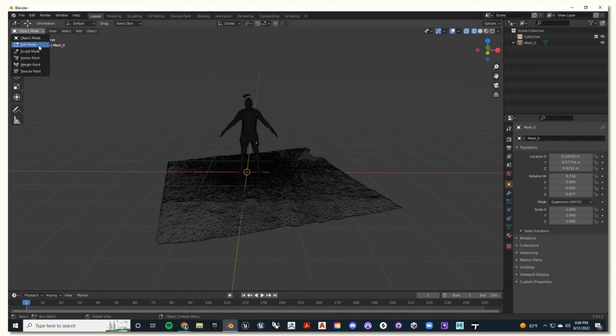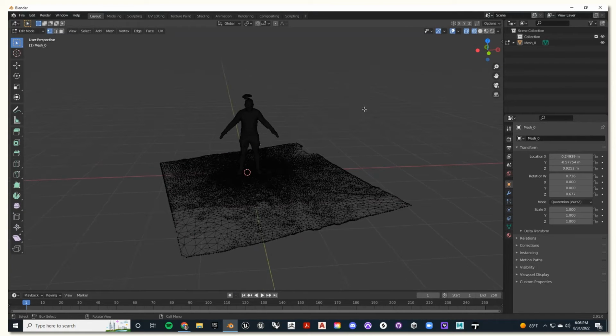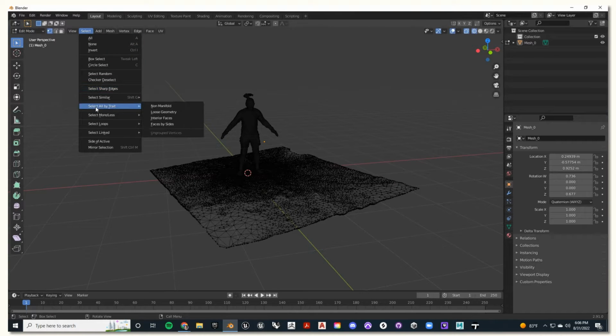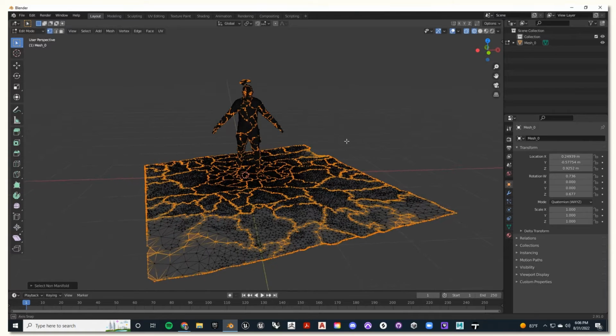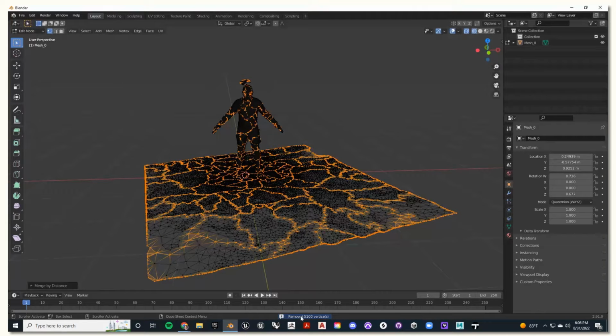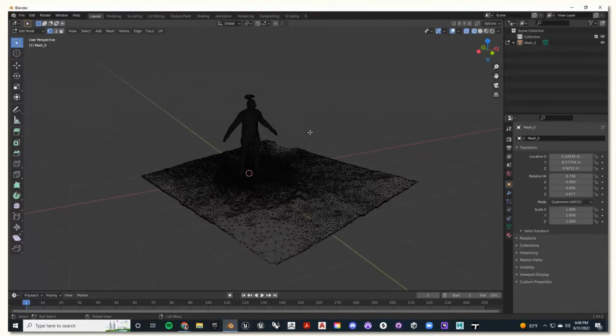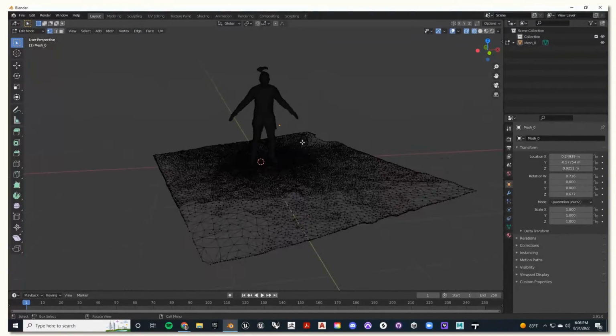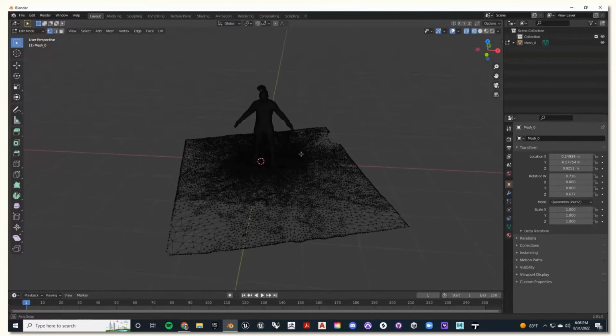Awesome. So now that's done, I'm going to remove any unwanted vertices by going to Select, Select All by Trait, Non-Manifold. Then I can go to Mesh, Merge, by Distance. That removed 5100 vertices. That's awesome. Okay, our next step is going to be cleaning up our mesh. As you can see, there's quite a bit of roof at the bottom that we'll have to remove.